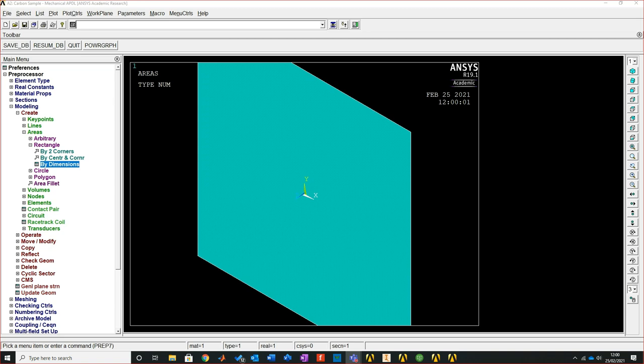Good question. So I'm just going to pan this back. I'll answer that. One of the groups just asked, is it possible to load the surface model as an IGES? Very true. It is possible to do that. You can import it directly in. However, it does become problematic. The system does read it, but it can lead to some levels of crashing.